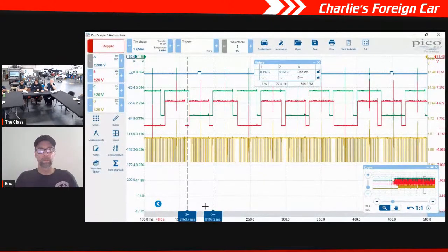Once it starts, then we start advancing the intake cam, correct? I'm not seeing that here, because when we were activating it, it's getting closer to the crank position, right? Not farther away. I think the exhaust is a negative value and the intake is a positive value that wants to get to 0, which would advance, right?